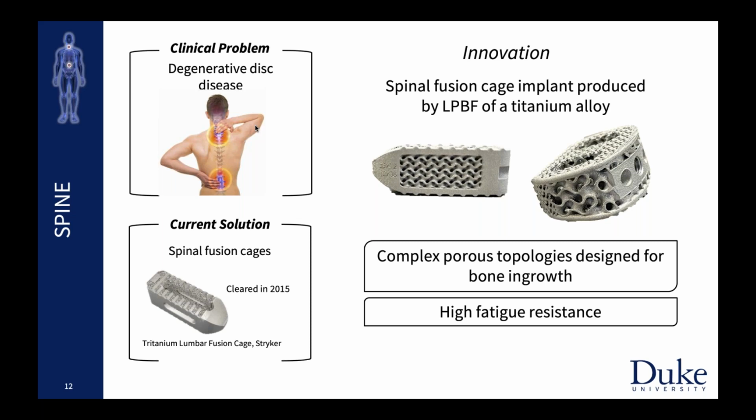So what surgeons do is they cut that disc out and they place a titanium 3D printed scaffold between your two vertebrae. That scaffold promotes the vertebrae to attach themselves. So you lose that range of motion, but the good news is you lose all the pain that you had. It's a similar type of problem. What's really fascinating about this problem is you need a really, really high strength structure that's porous that also will allow you to have bone growth through it. Because if the bone doesn't go through it, you don't fully fuse those together, and there's a chance that it will break eventually.